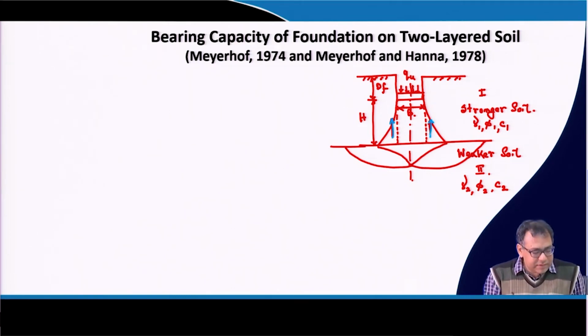Okay. So, that shear resistance we have to calculate. Now, again, when this soil will start to move, as you see the original failure line, the soil is moving in the outer direction. Obviously, the soil will move in the outer direction. So, that means there will be a passive resistance that the soil outside this failure zone will give, because the soil is trying to push in the outer side, to two sides of the foundation. So, those soils will give you a passive resistance.